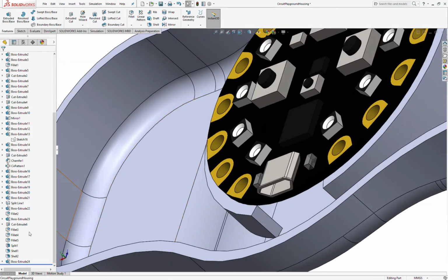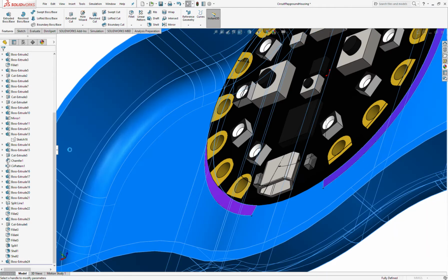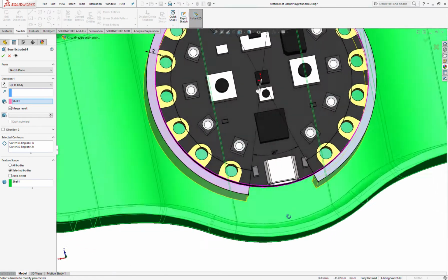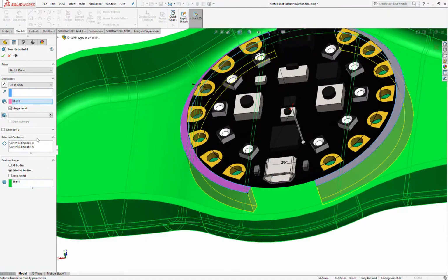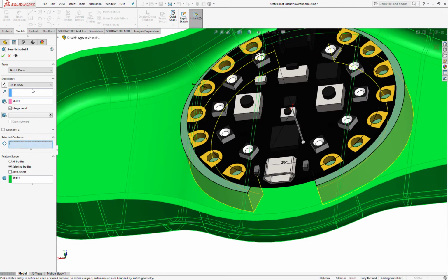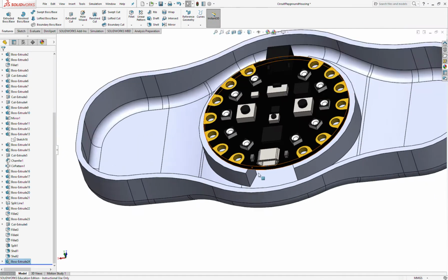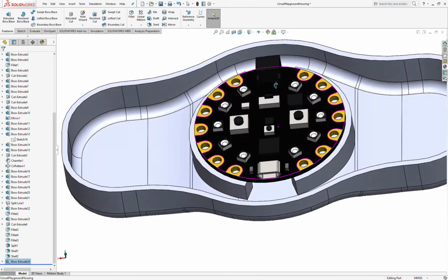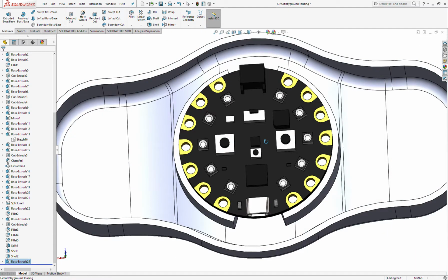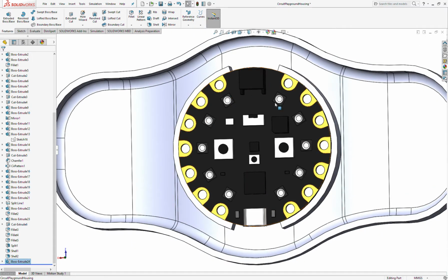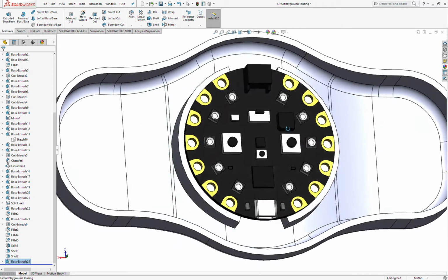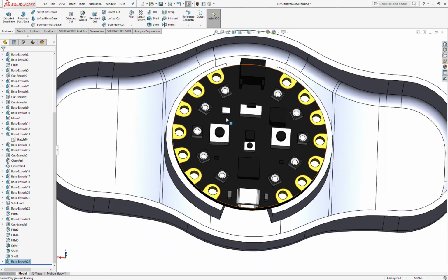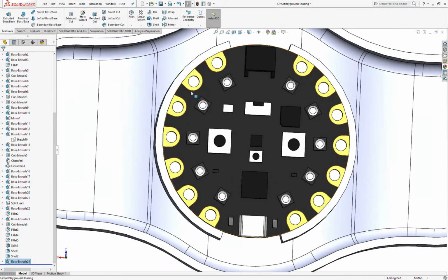Whoops. Not so good. Something happened with my contour selection. There we go. Alright, that's what we want. So we've got nice good supports under there. Now we're actually going to make use of these supports for two features: a holding feature and an alignment feature, an indexing feature. For indexing, we're going to do a couple pins, maybe there, there, there, and there. And then we're going to do some little holding tabs as well.